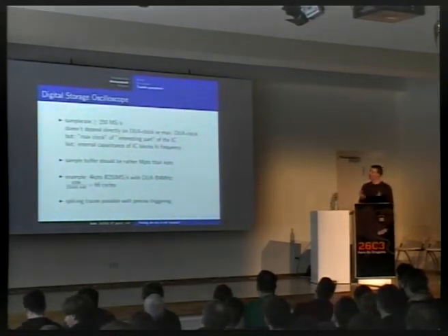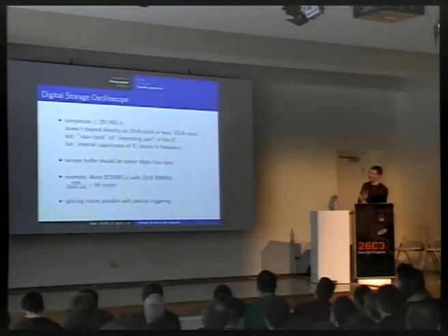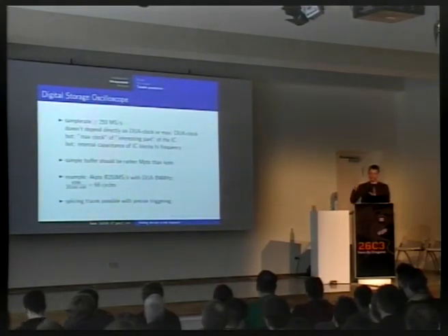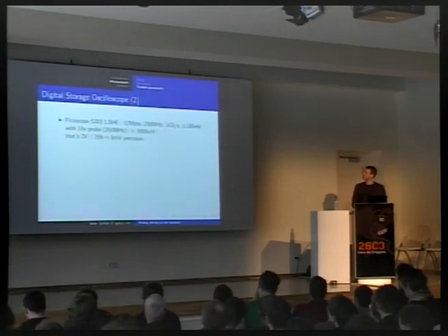Of course, if you can't afford a higher priced scope, you can still do the same plain text and trigger at different offsets and then splice those traces together. But it is, of course, more work.